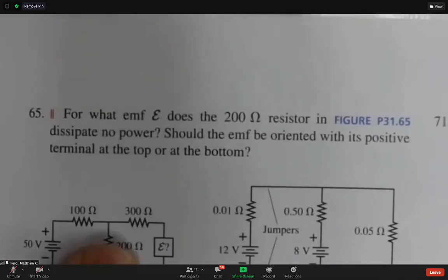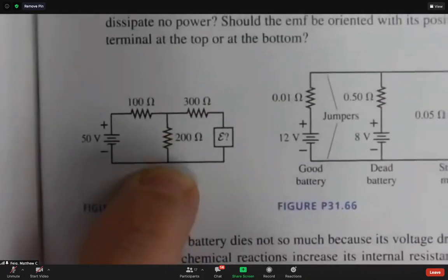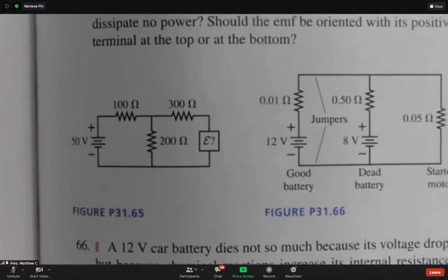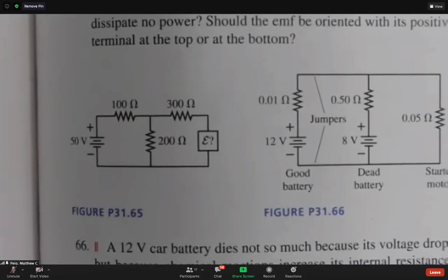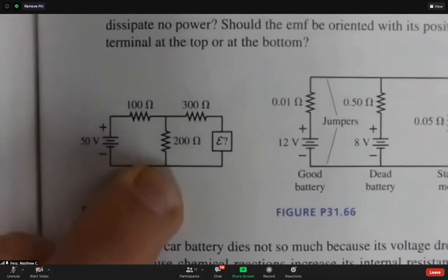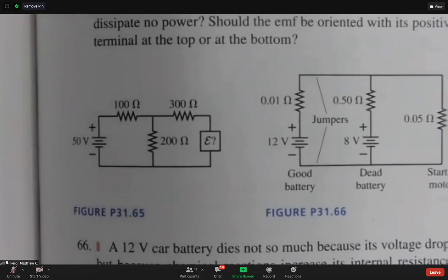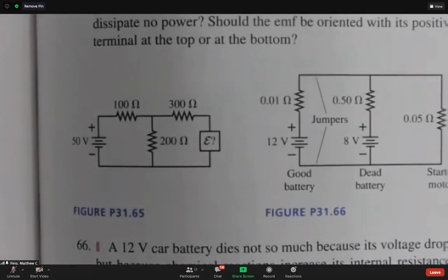And if you connect a wire between 2 points at the same voltage, it's the same as if you didn't connect that wire. If you connect a resistor between 2 points that are at the same voltage, and you take that wire away, it has no effect on the behavior of the circuit. You might keep that in mind if you try the homework extra credit, the circuit resistor extra credit. The one with the cube in particular comes to mind.